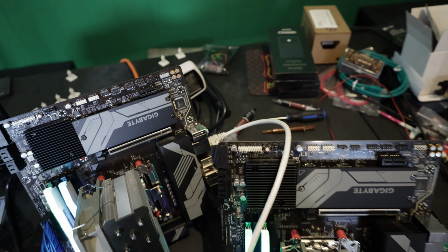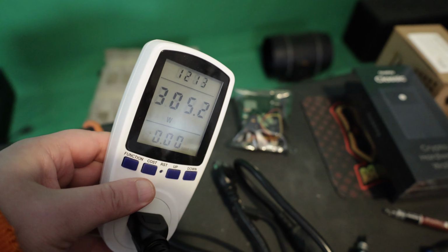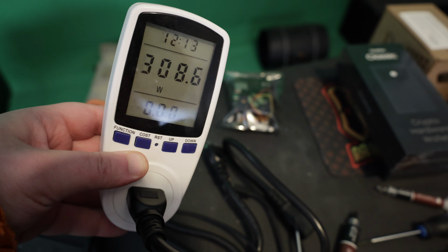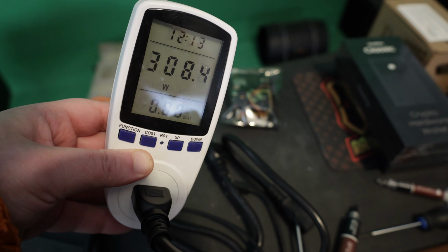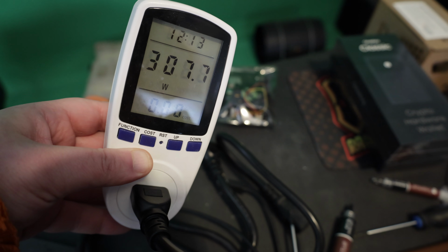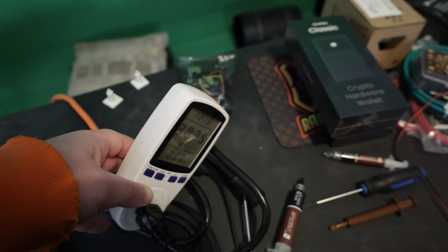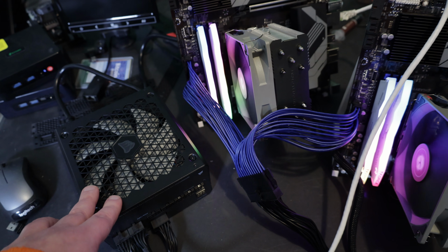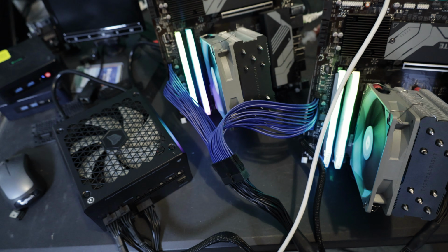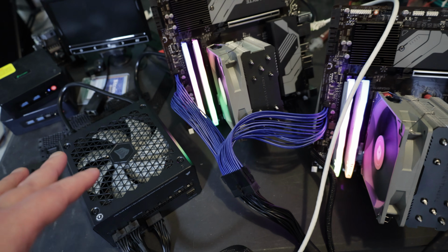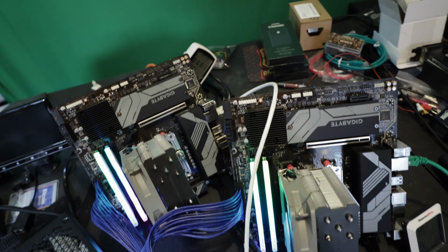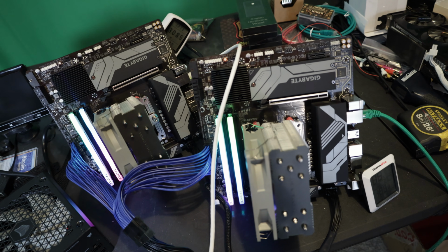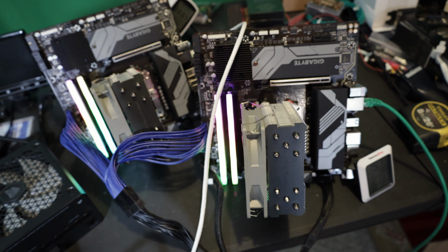So let's take a look here at the power. We are now at, wow, 308 watts. Because we are closer to the peak efficiency of the power supply, we did lose some power there, so that's awesome, just as I expected. That's why I do this. This is actually a 750 watt power supply. I think around a 600 watt power supply would be better, because as you can see, we're at 307 watts, so we should drop the power a little bit more based on the power supply that you use. So that's one thing, guys.